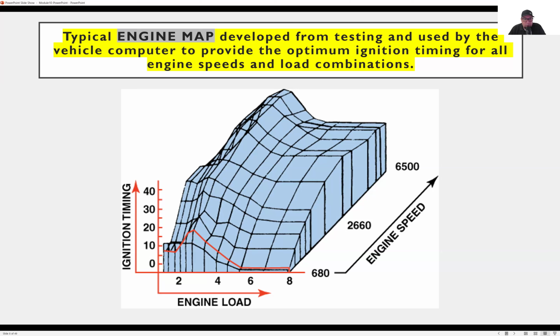Okay. And then if you tune your engine and you want to make it faster, you go to a high performance shop to get it tuned, and they're going to do the opposite. They're not going to care about emissions, they're going to care about horsepower and torque, and they're going to increase the power. But again, we're still doing the same thing. We're reprogramming the computer to determine when your ignition should spark, and how much fuel can be given to the engine, as far as how long the injector can be open, how much time. So there are various things we can do to increase power or reduce emissions. Right. And that's what engine mapping would do.